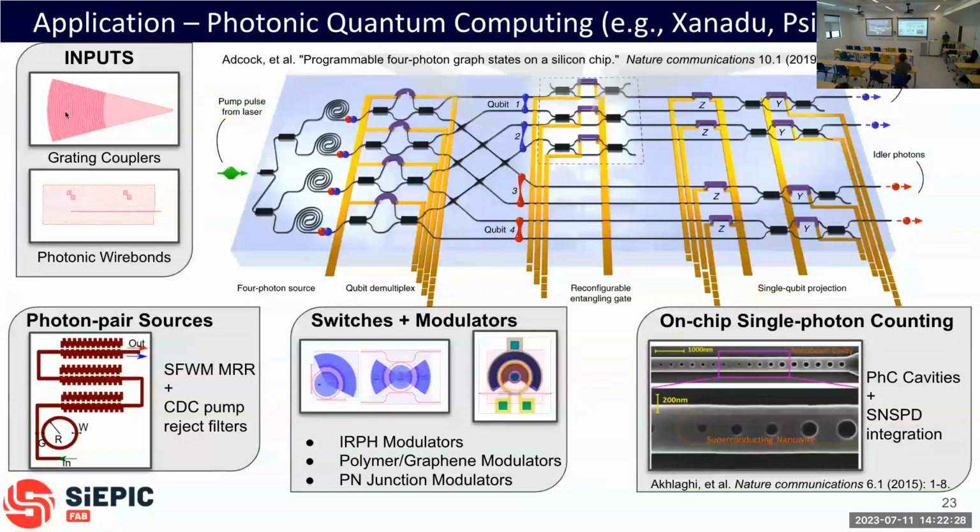So the parts that we talk about here are, how do you get light into the chip? This is one challenge that we work on: you've got this laser, how do you even get it into the chip? We spend a lot of time thinking about that and doing it efficiently. Then generating these things. This is the device that we're working on, this little ring here. And then also filtering out this green laser pulse. You have to get rid of it, because you have a high power laser and then you have single photons. It's like the worst possible case you can imagine in terms of filtering application, super high powers and one photon. So making really good filters turns out to be a really good challenge for engineers like me.